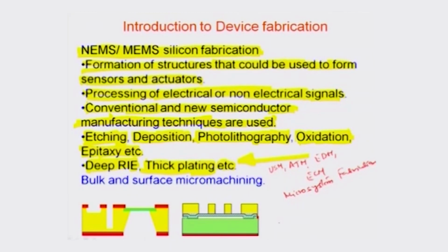manufactured components or devices. So, if you look at all these machining processes in bunch, they can be categorized either as bulk micro machining processes or surface micro machining processes. And the bulk processes really are about the subtractive removal of material or subtractive processing of material from a wafer surface.